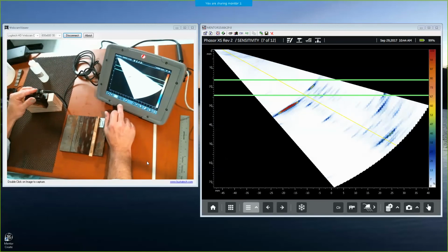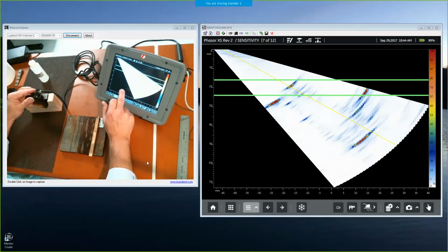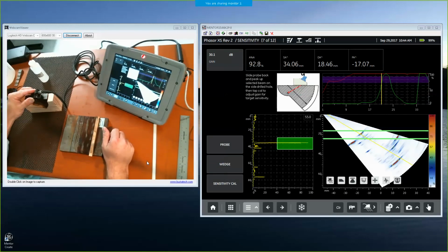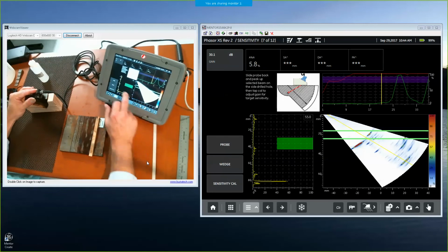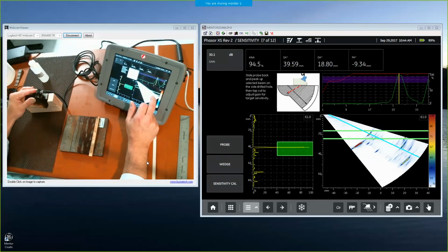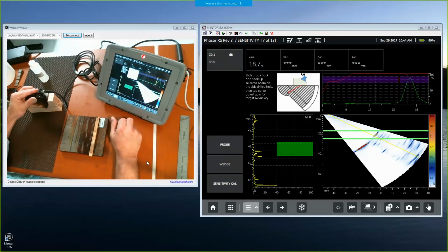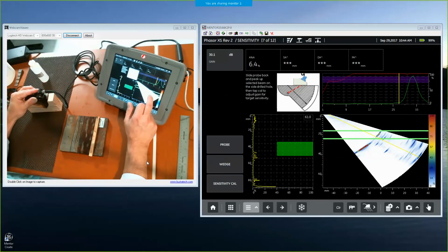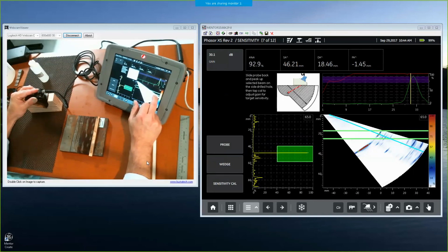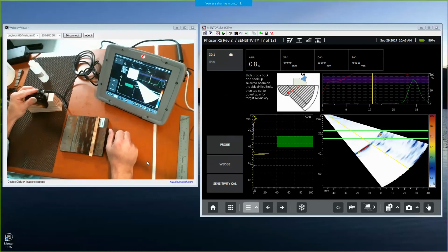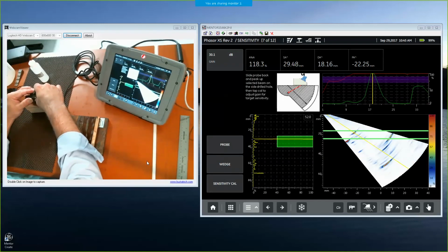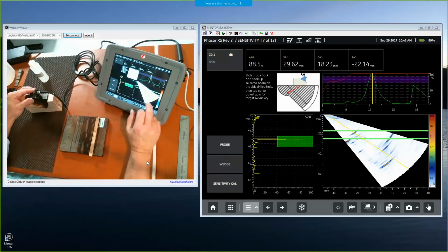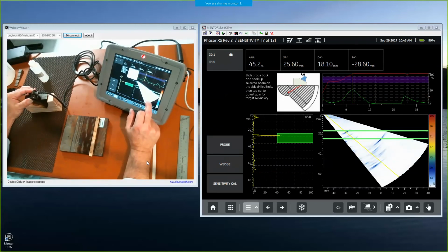So if you go to your A scan right there, when you go to those different angles, are you still getting 80% even off the selected beam that you're at? Well, as I move, the A scan is always going to reflect whatever the selected beam is. So, yeah, as I walk the indication to a different beam, of course I lose it on that A scan. Let me get a hold of the beam selector. Let's see, there's your 80, 90%. If I bring it over here and bring that back, it's all pretty sensitive to the alignment of the probe and coupling pressure too, but you can see how it's pretty well on for all the different beams.